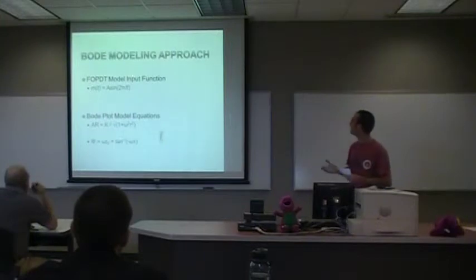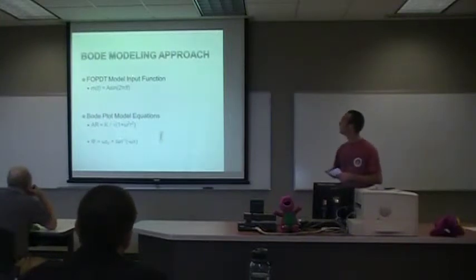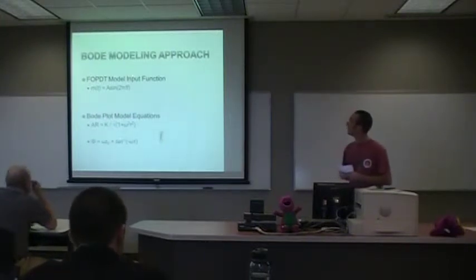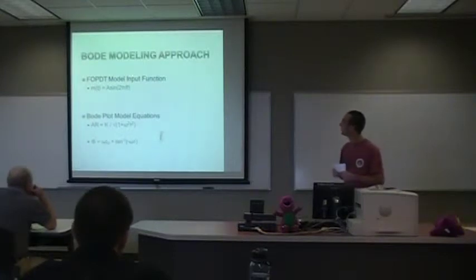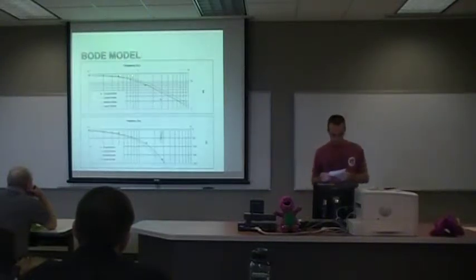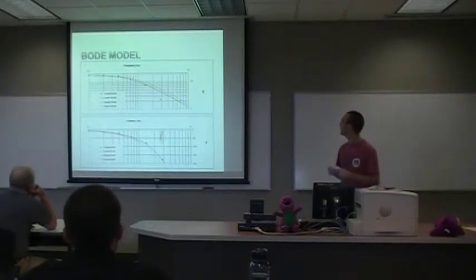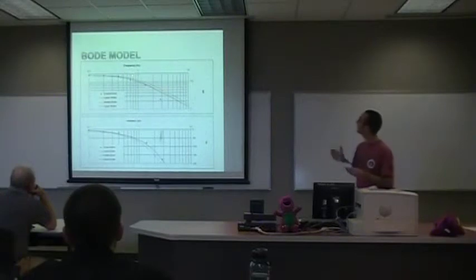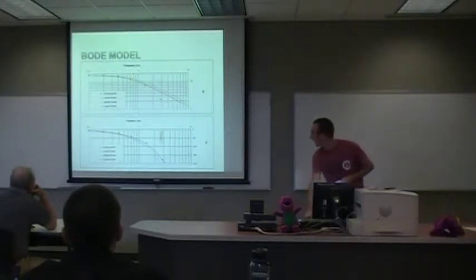And this is the input function for the time response, which is a sine function. And these are the two model equations for your amplitude ratio and your phase angle. And this is the Bode model, which for all three curves shows you your model gain, your dead time, and time constant.